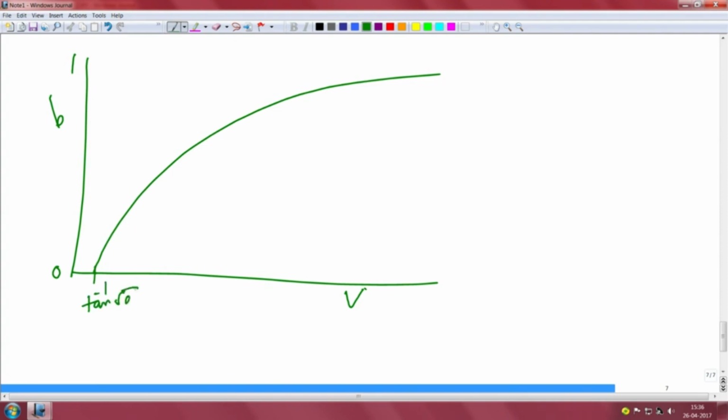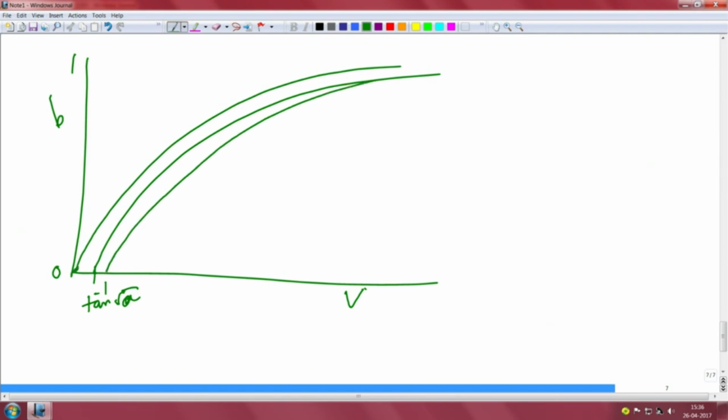and I am trying to observe the range of values of these curves. So, for a symmetric waveguide they start here, and for a highly asymmetric waveguide A is very large, tan inverse of a very large quantity is pi by 2. So, it can go up to pi by 2. So, this is 0, this is pi by 2. So, say this is the fundamental mode, all the curves corresponding to the fundamental mode for various values of asymmetries will fall in this, A equal to 0 here and A equals infinity at the other end.